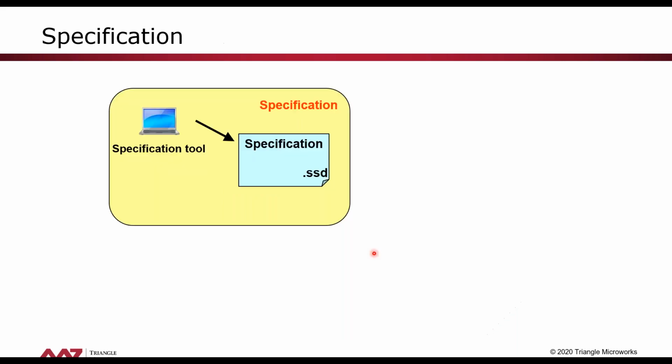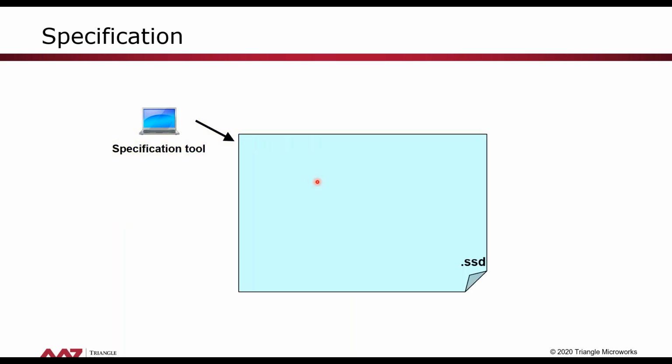Okay, with that, let's now get into the specification stage, where we use the Helix STS as a specification tool, and we produce the variant called System Specification Description File, SSD, a variant of the SCL files defined in the standard. During this phase, we are mainly filling in this first part of the SCL file, which describes the substation section or the functional part of the system.